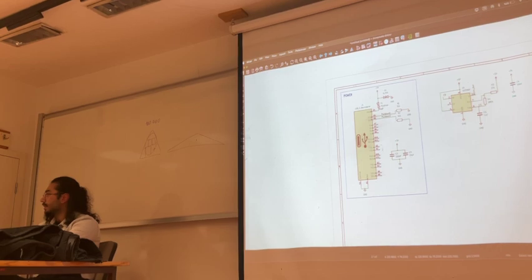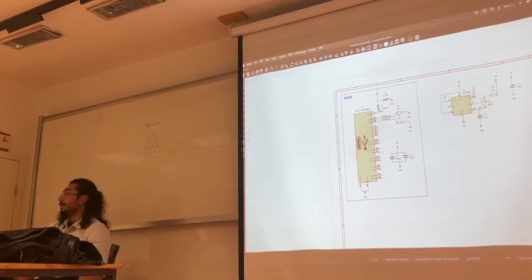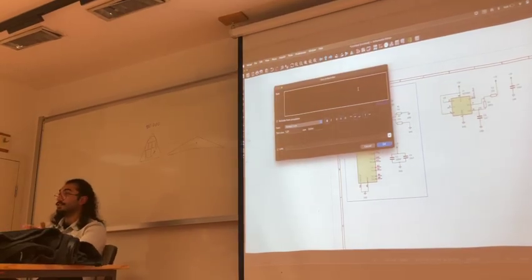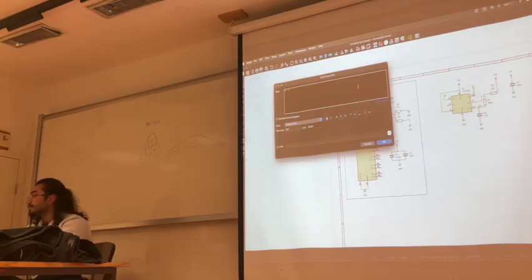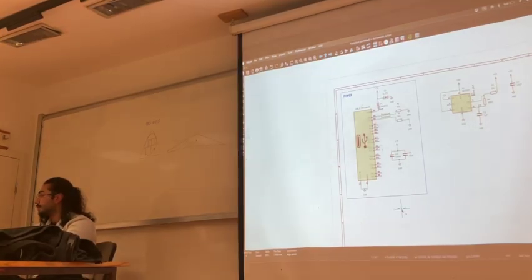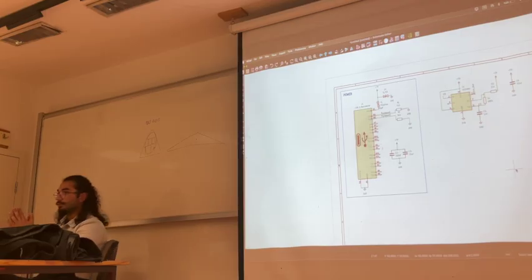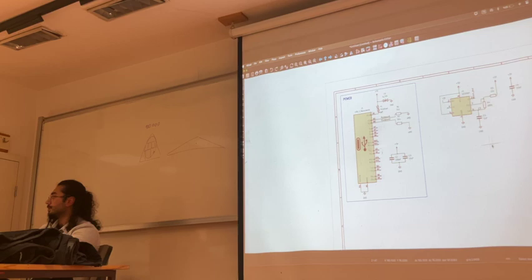I also suggest, let's say you make a filter. When you make a filter, I would suggest writing its formula, like writing its gain using a label here. Let's say AV is 10, a gain of 10. You have a stage of 10 gain. You add it here, under the things that you're going to make. So make it conventional, okay? It will help you and other engineers very much.